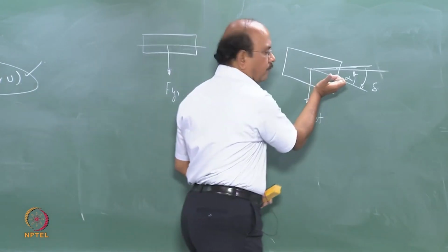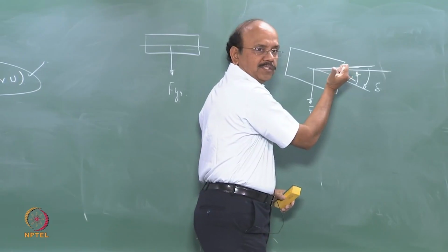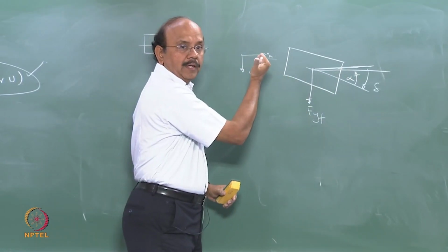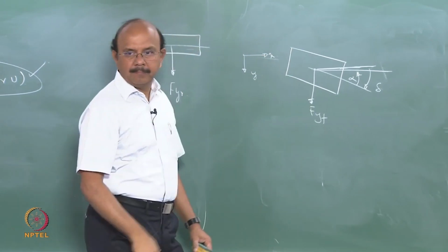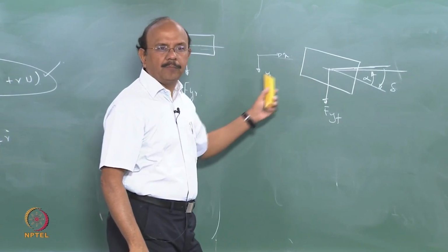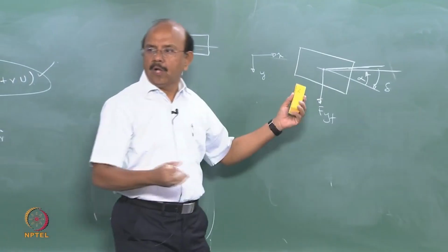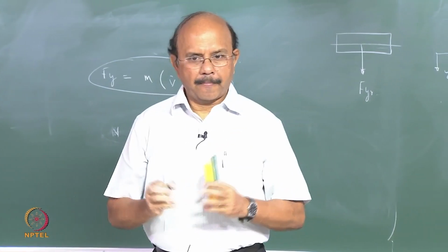The slip angle is in this direction, which is the negative direction, and the force is created in the positive direction of y. We know physically how Fy is created, but we'll be careful with these negative and positive directions when we write down the equations.